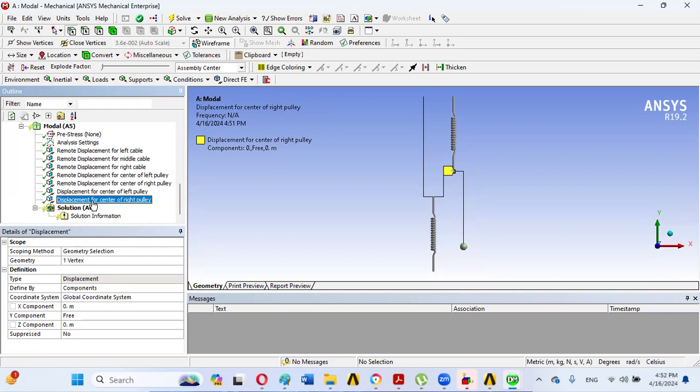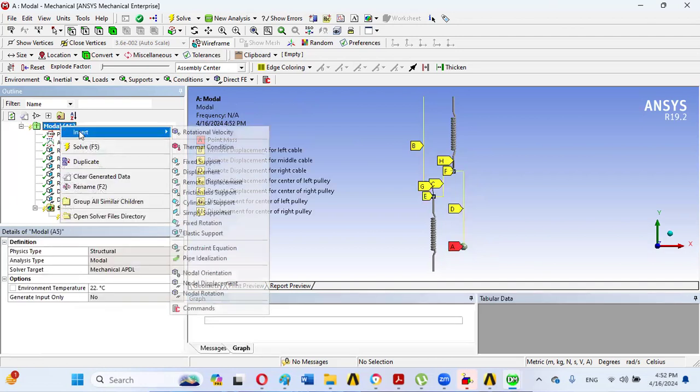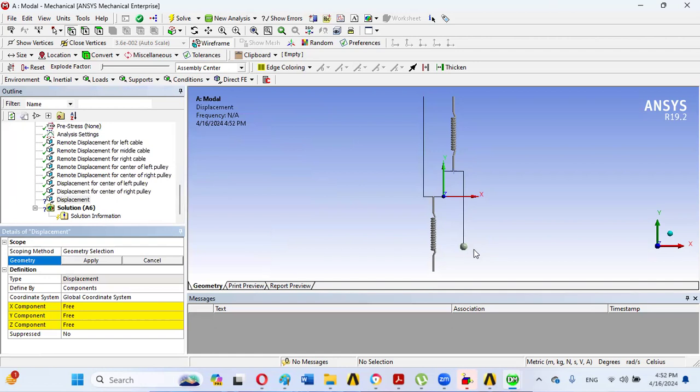So the displacements have been applied, and one more displacement constraint will be made here at the location of this end mass, so that this point is constrained to move along the vertical orientation. So distinctively we can apply displacement at this location at the point of end mass.